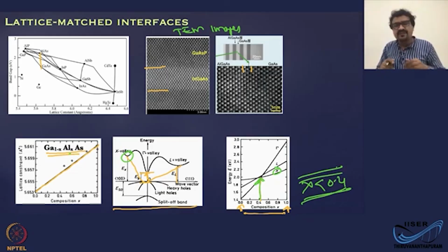That is the overview of this gallium arsenide, or III-V, heterostructure. You can see how perfect those interfaces are, and you will see very soon that because of such a perfect lattice-matched interface, the electron also possesses really superior mobility and other transport characteristics.